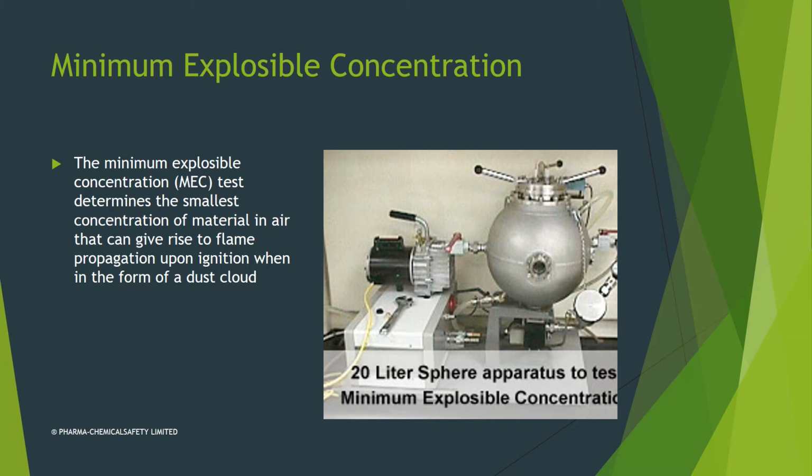And that is going to help you design your process. This parameter is going to help you, and that's one of the critical ones. Like I said, it's very critical, especially in those types of industries, food, pharmaceutical, and chemical, because you have these powders as a raw material. So now you need to use these parameters to know what you're gonna do in terms of deflagration prevention.